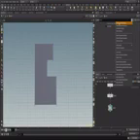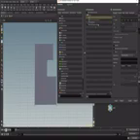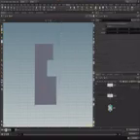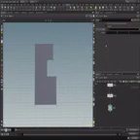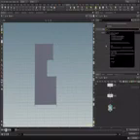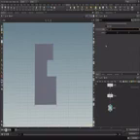So we can do this by dragging in two O3 vectors. And the first one I will be calling bounding box, and the second one I will be calling the centroid. There we go. And to get the bounding box, we can have this bounding box expression, which will be referring to itself. So we can do like this. And then we want to have the size for the x direction, so x size.